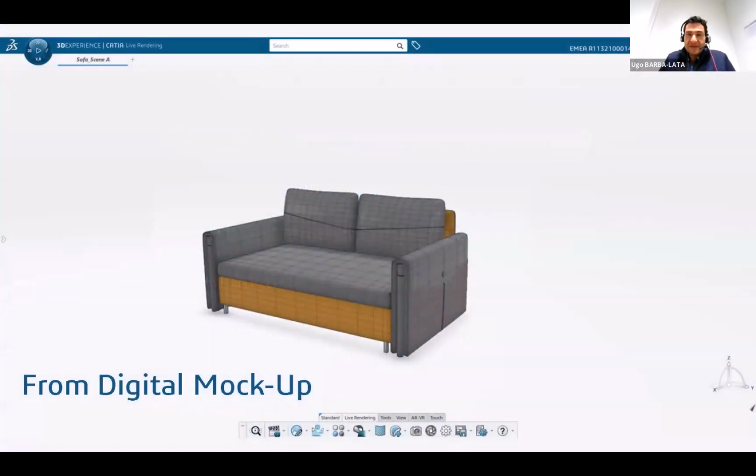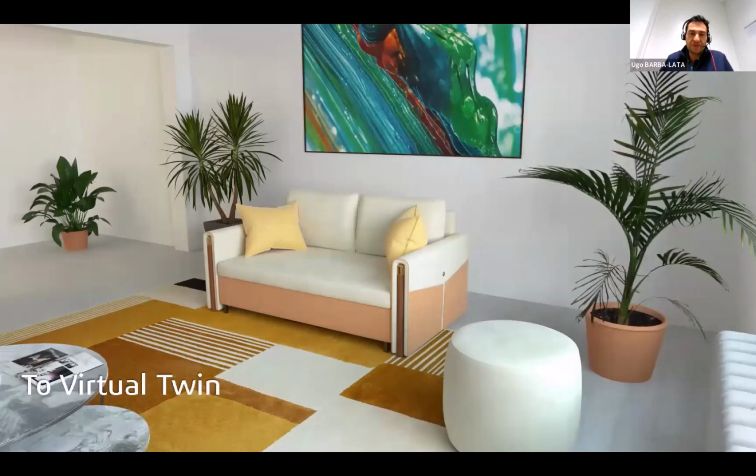And so first, as I was explaining, you have CAD data. This is how your data looks when you are designing. And we call this a digital mockup. And we will turn this into a virtual mockup. And here, what you have is what we call covering materials to apply the correct material appearance on the geometries. We have an ambience which is sending and creating lights and realistic appearance around the model. And also you see here some scenarization, or what we call staging, where we place the product in a specific context to create this realistic feeling and appearance.